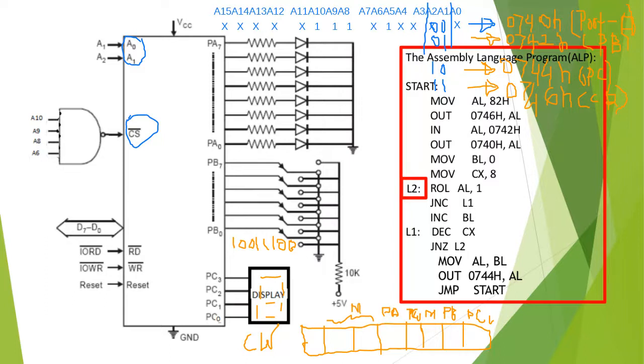And this is by default 1 to make it active. Okay, and port C lower is used as an output port. So this is output, and port B is used for input switches. And mode is simple input output mode, so mode 0. And port C upper, there is no use, so it is don't care.